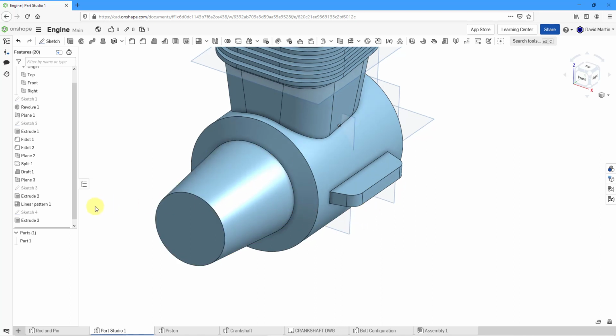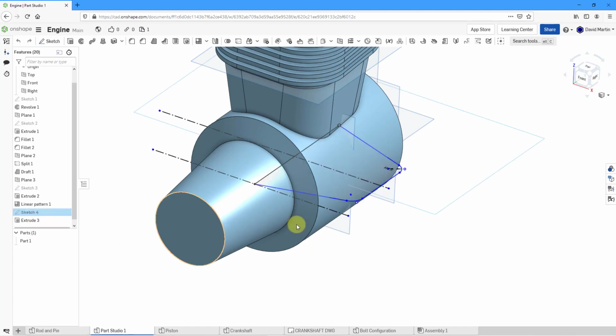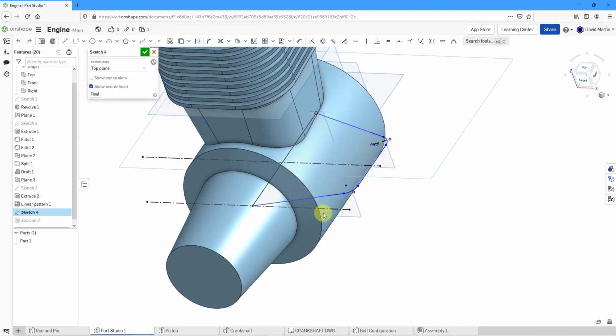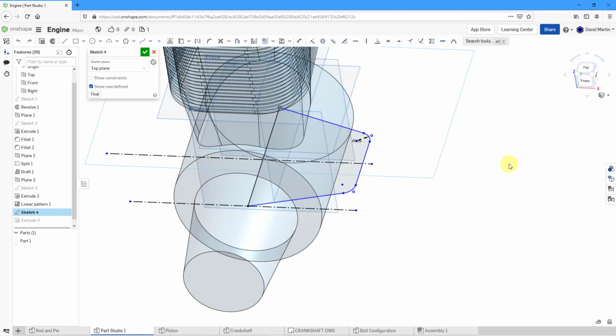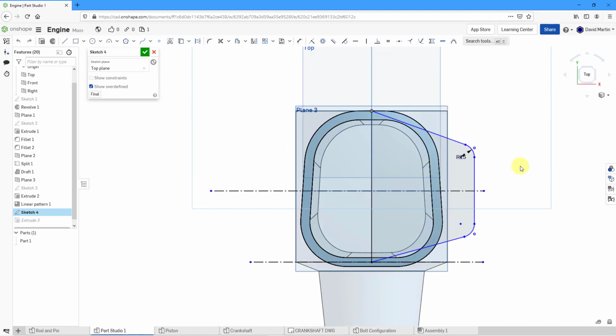You know what? I don't think I fully dimensioned that sketch. Let me go back to this and edit. Yeah, I have all those blue entities. What was I thinking? Let me change back to translucent, and let me right click and view normal to my sketch plane. Yeah, why did I get out with all those blue entities? All right, let's see. I want to have some dimensions.